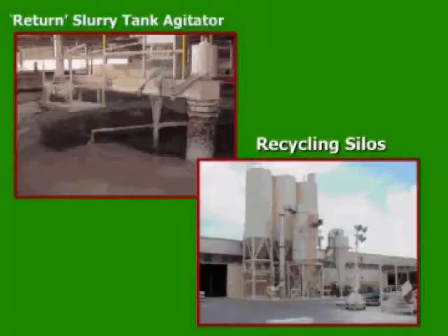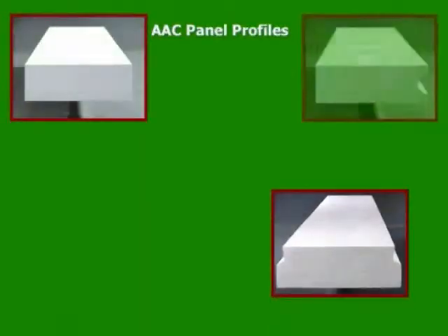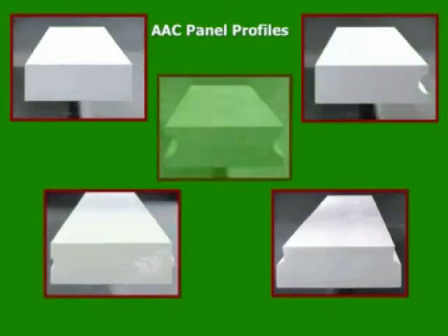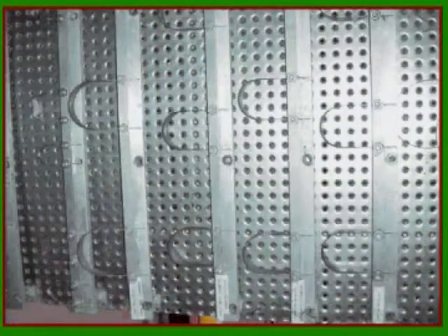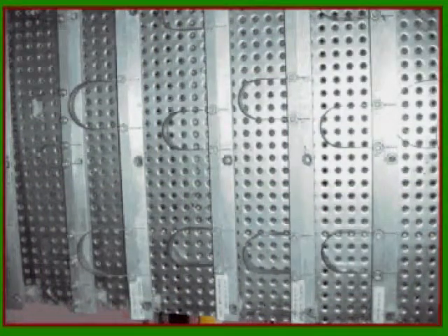raw materials. In order to cut those profiles into our wall, roof or floor panels, we use those profile knives right after the wire cutting process. This is a vertical load-bearing panel without a profile. This is a vertical load-bearing panel with a half-round profile to add a vertical reinforcement in the center of the wall thickness, in a spacing required by the engineer, which is in accordance with your local requirement.